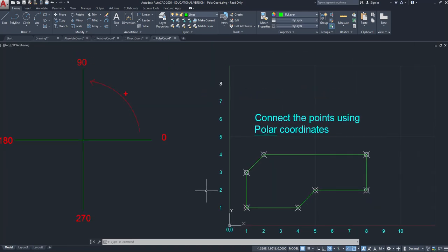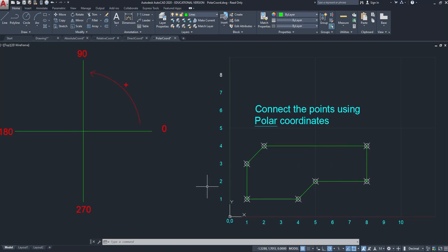And so we're going to do that, okay? But let me just say, the way that I prefer to create diagonal lines in AutoCAD, instead of thinking about what angle this is at, is to use polar tracking. Do you see my mouse down here? I have a setting called polar tracking, okay? If it's blue, it's turned on. If I click on it and it turns gray, it turns off. Blue on, gray off. There's a little arrow next to it, and if I click on that, you'll see 90, 180, 270. I have groupings of different angle increments.